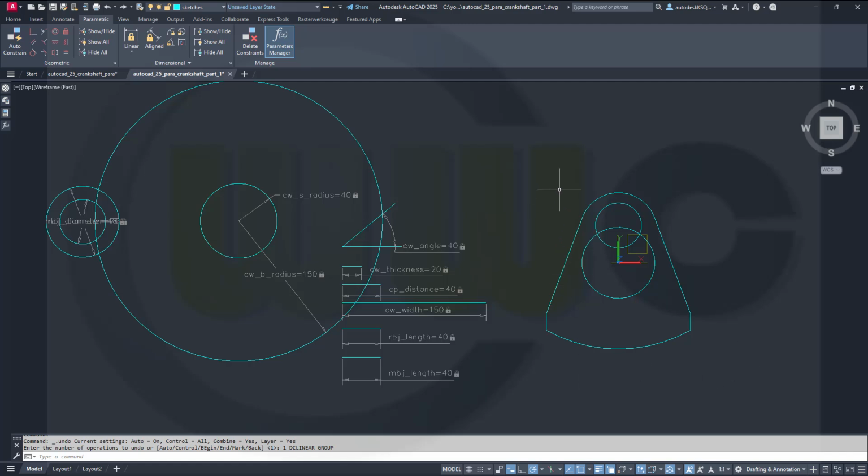I've just noticed I've forgotten one length here. So I will need another line, put it right here, and this will be the vertical height of this one. So let's fix the start point, then go for linear dimension from this point to that point, and this length should be 167 millimeter.